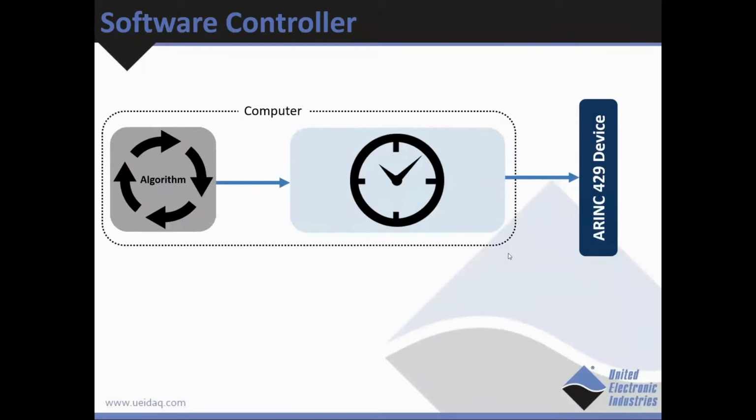Typical update frame rates of ARINC-429 devices are 25 milliseconds, 40 milliseconds, and 66 milliseconds. Avionics usually show inop or inoperable when 2 consecutive frames are missing. For example, when the updating thread is delayed for more than 2 periods. Can your software algorithm keep up with all the labels and not miss timing on any one of them?